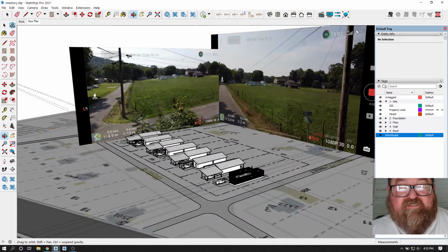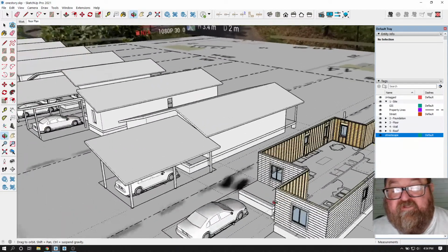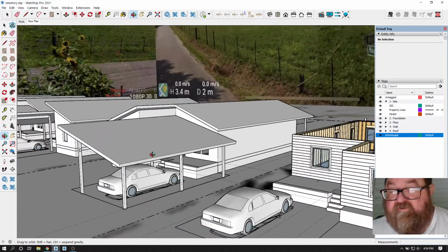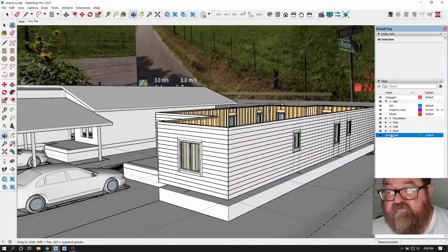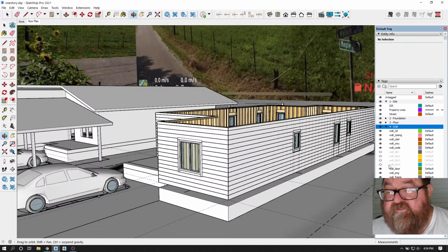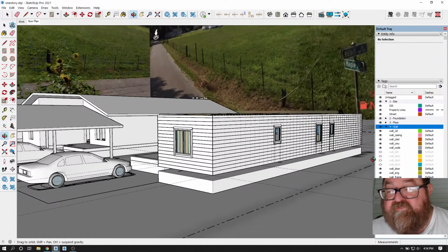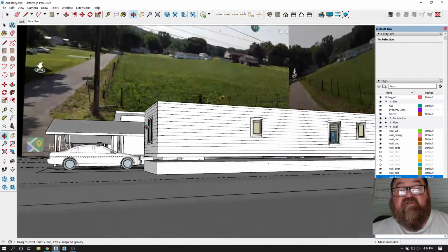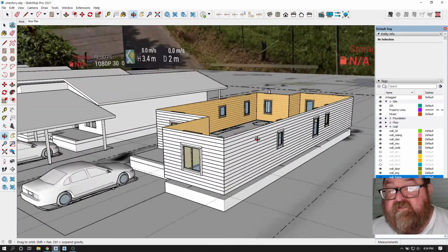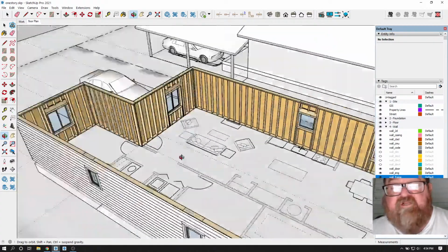And that's always a challenge in SketchUp, how to make your models look like they're rendered. There's a few tricks you can do. You can use shading and things like that, and use colors. The other thing I was explaining earlier was that sometimes you can see the studs through the siding. You can just go in and turn off that layer of wall framing when you get ready to do your sort of rendering, however you want to do it. But then of course, when you start to count your studs and you're doing your takeoff, you can just turn that layer back on.